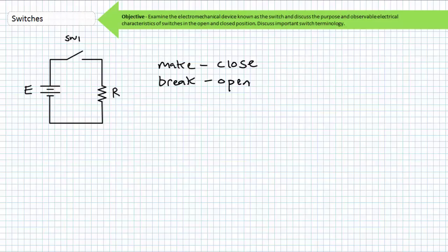from continuing. As we'll learn in the circuit protection devices lecture, sometimes pretty exotic methods are used to extinguish this arc. Additionally, the act of making the connection must occur as rapidly as possible, but this rapidity brings with it the possibility of switch chatter or bounce. Imagine parking your car at 60 miles per hour. Chances are cars on either side of you, in the front and back, might show signs of mechanical wear. We'll learn in later lectures that physically moving contacts can be replaced by power electronics devices with no moving parts, such as a solid-state relay for high-speed switching applications.